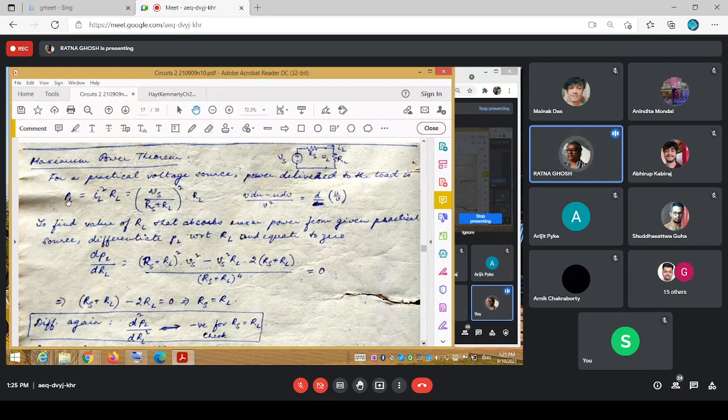Further on, to find the maximum, when would you have maximum power absorbed? For a value of RL. So naturally, d/dRL of PL. That is what you would do. In order to do that, and this is your standard rule for the differentiation, u by v. Just substituting that here, you would get this kind of a relation.